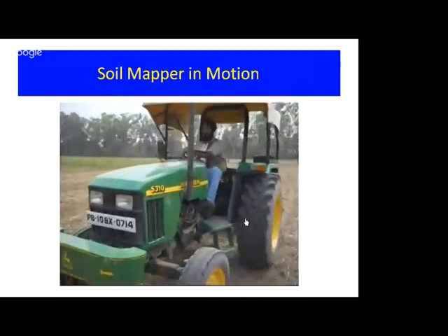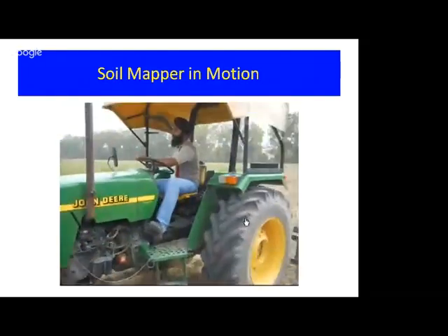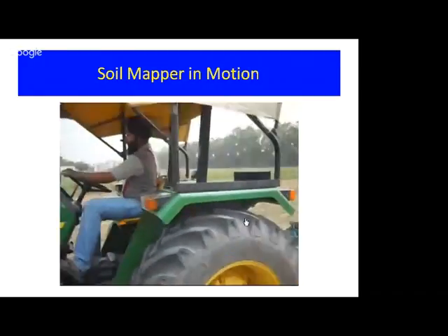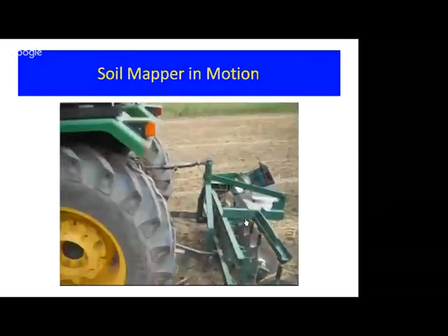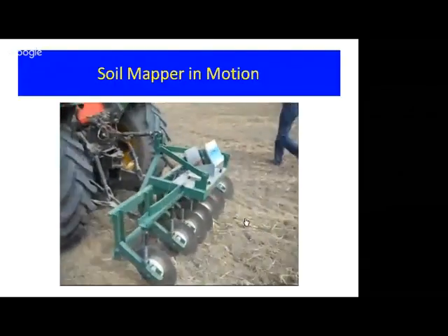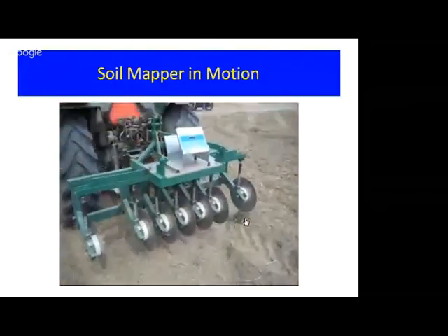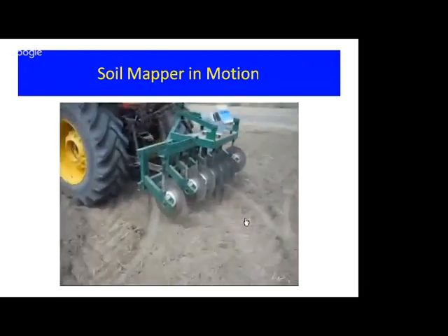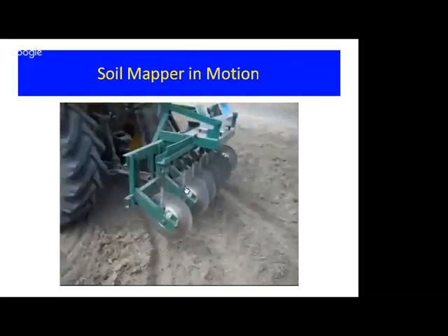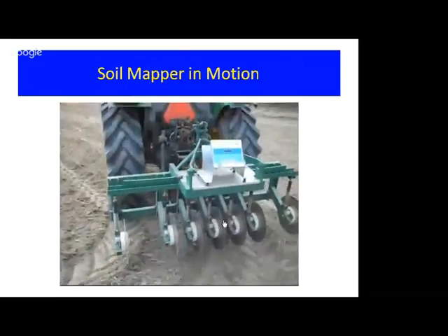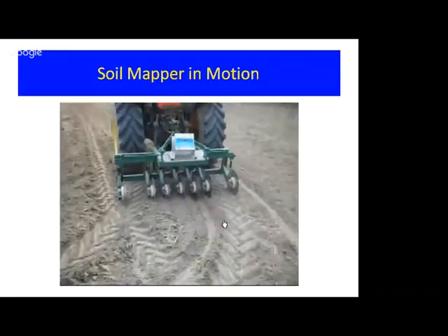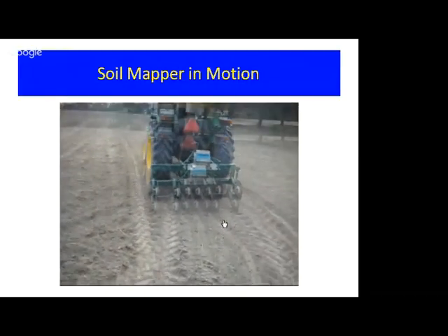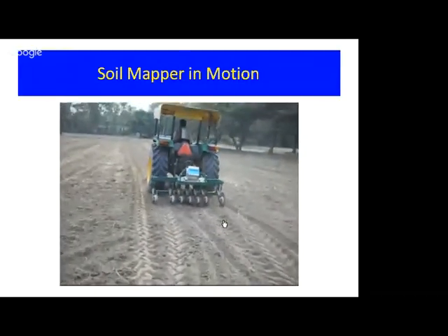The whole machine is an automated machine. There is an inbuilt robotic and pneumatic mechanism of the tractor, which is used for lowering or raising the depth of the electrodes, and the rest is all taken care of by that embed system. There is automatic injection of signals in these electrodes. What you are seeing, the coulters, 2 coulters inject the current signals, and the other 2 receive the signals back. And this array that you saw was a specially designed array.